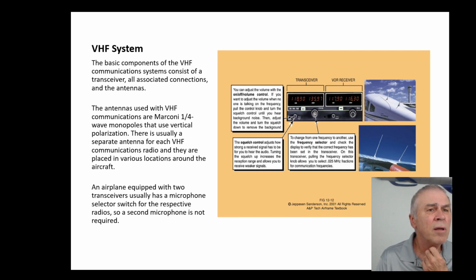Redundancy. And they are placed in various locations around the aircraft so that if your VHF signal is blanked by the wing or something else, you can still get communication maybe from a different angle.